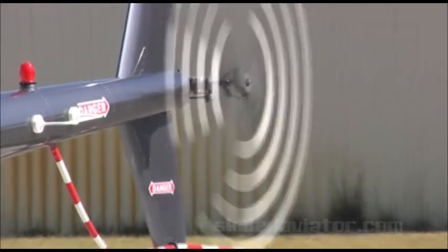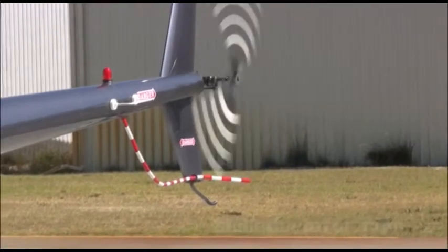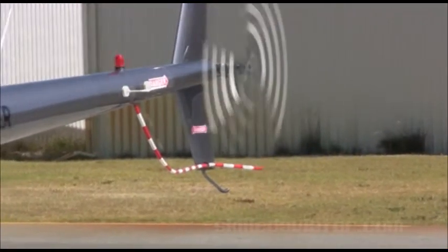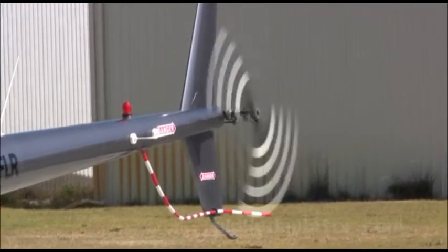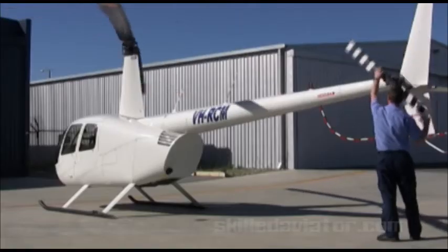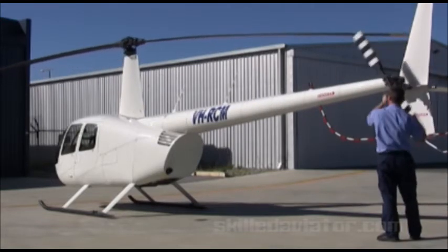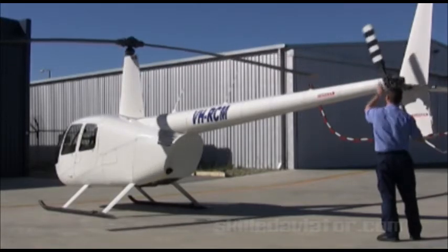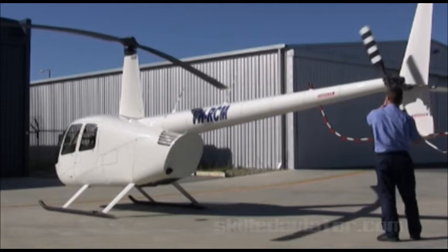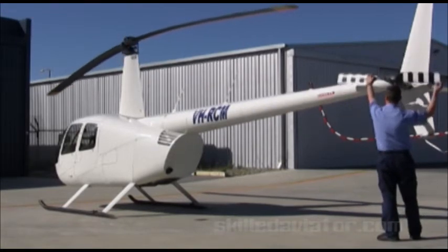Now, to recap, the main purpose for the anti-torque rotor is to provide the required thrust to overcome main rotor torque. The anti-torque rotor also enables the helicopter to have hover turn capability and balanced forward flight. While the tail rotor is normally linked to the main rotor via a system of drive shafts and gearboxes, so both are usually connected to the same transmission, meaning that if you turn the tail rotor by hand, the main rotor will also turn.